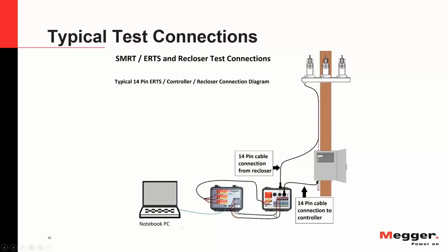What you have to do is get in the way of that cable so that you can take the signals from the panel, and feed the relay with the signals that you want to use from your test set without having those signals go through the circuit breaker mechanism.